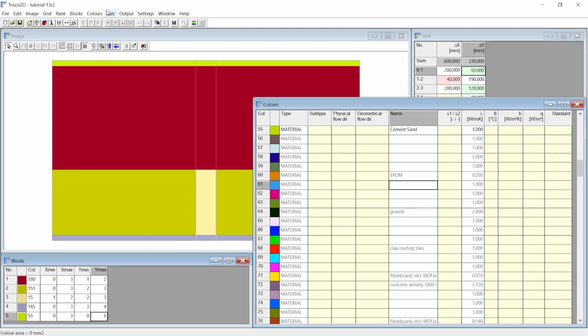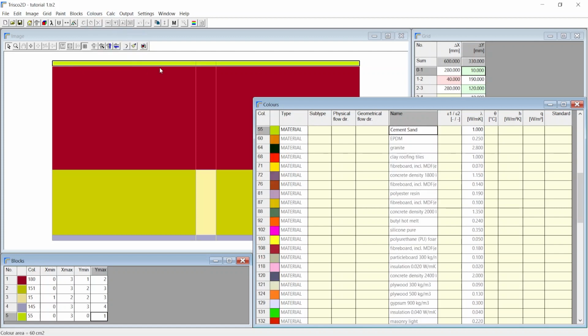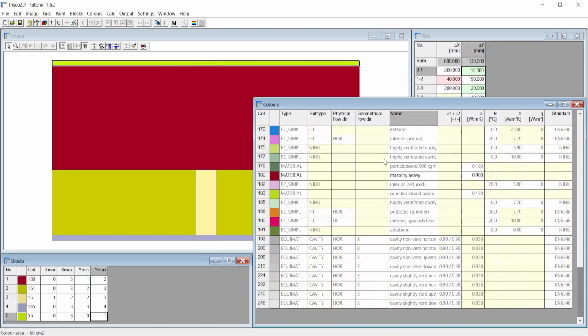If we choose List Defined in the Colors menu, then only colors with predefined properties from the color database are visible. For the assigned colors you can also change the name or properties as they are in editable format. But you need to note that any change you make here is only restricted to this project, as the changes are locally made and won't affect your future projects.